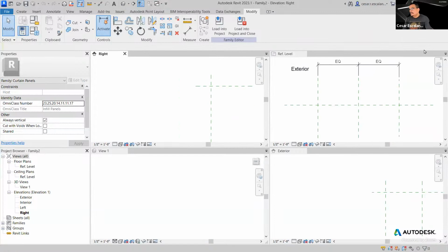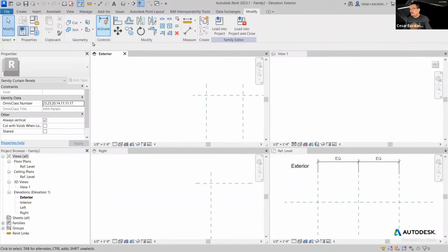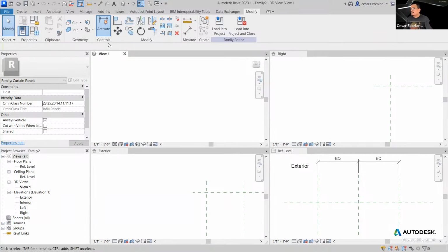And notice, maybe this is a little tip, when you have windows that are tiled and you want them in a specific order, like if I want the exterior one to be at this corner, select it, enable this, and then tile WT, and then it moves it right to the very first one. There's a way to rotate them. Select them, WT, then whatever is the active view, it takes the first tile.